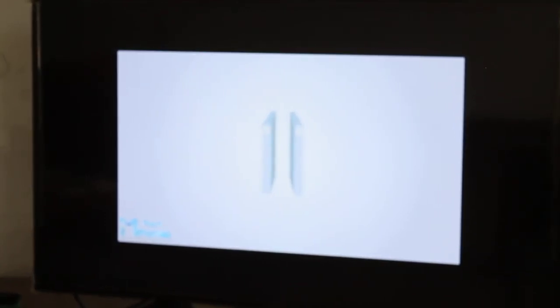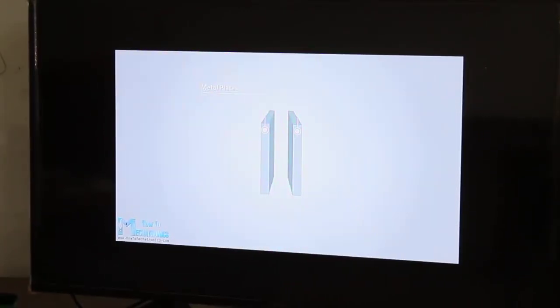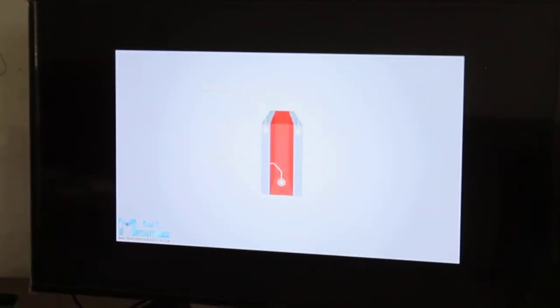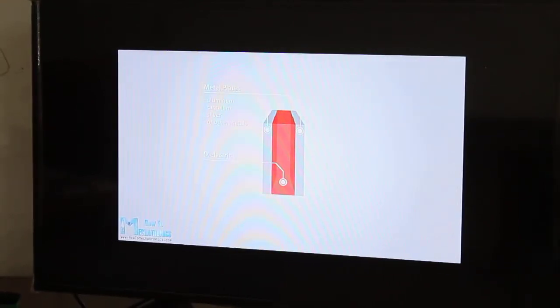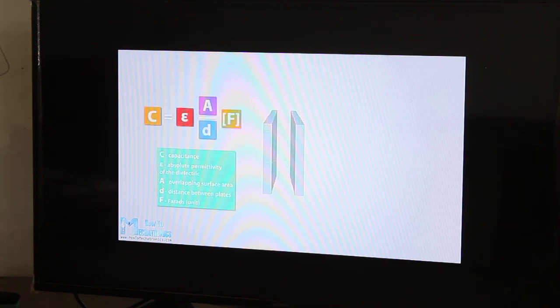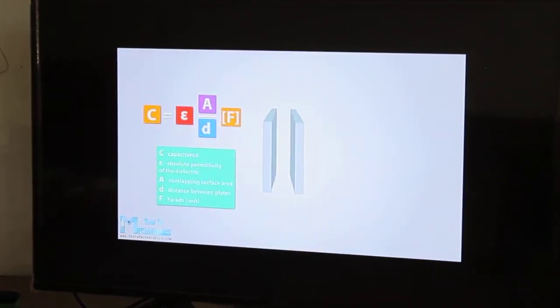That being said, now let's take a look at how a capacitor works. First, we can note that a metal typically has an equal amount of positively and negatively charged particles, which means it's electrically neutral. If we connect a power source or a battery to the metal plates of the capacitor, a current will try to flow, as the electrons from the plate connected to the positive lead of the battery will start moving to the plate connected to the negative lead of the battery.